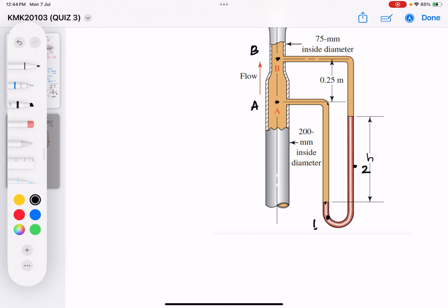So the pressure difference P1 minus PA should be density multiplied by g multiplied by h. If you select point 1 over here, which density are you going to use? Because here it was obviously manometer fluid, let's say mercury, and then after some time it was filled with the oil. Then you should ask yourself which density to use.